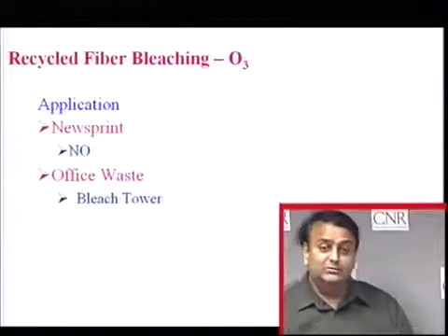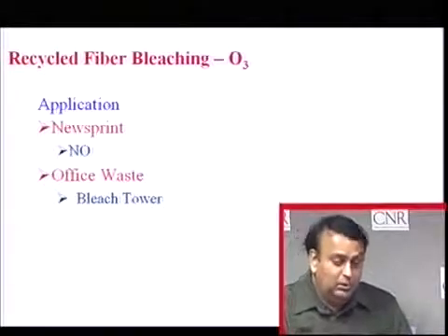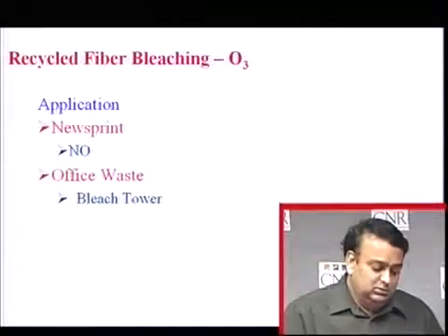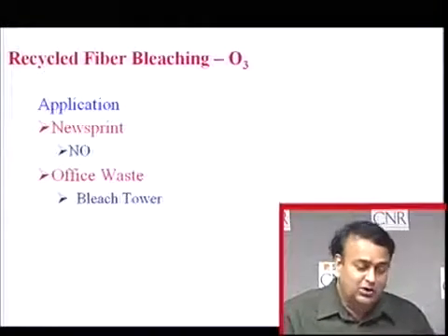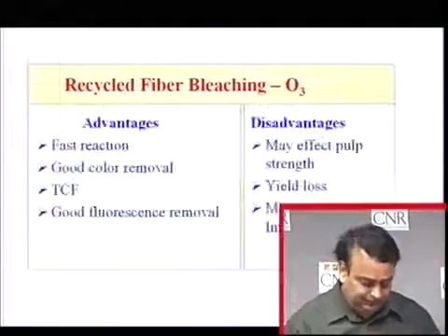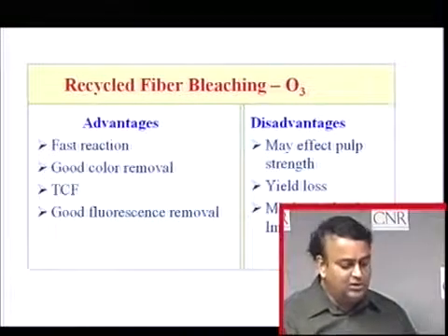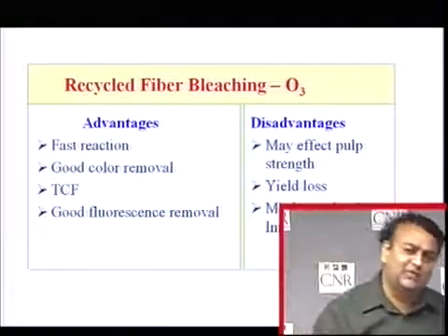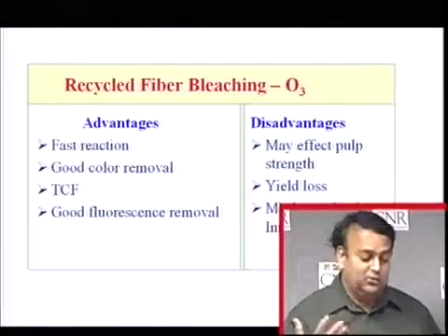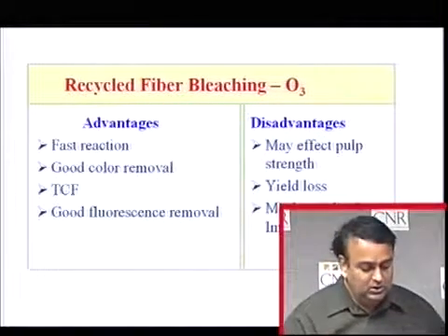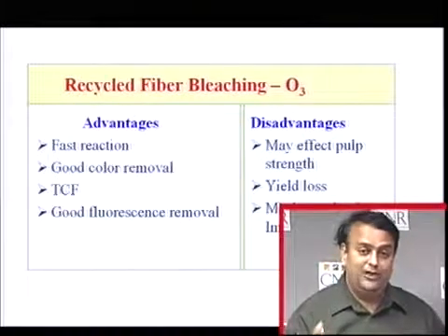Where do you apply ozone? Again, not for newsprint. For office waste, using a bleach tower, ozone can be used. What are the advantages? Very fast reaction, 5 minutes, room temperature, low temperature, good color removal, and a TCF label, total chlorine free label.